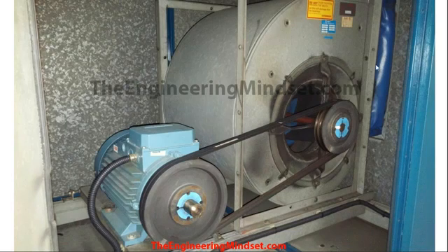So just to bring you up to speed with that, excuse the pun, we've got the motor here, then we've got the fan over here. Now these two are connected by the belt pulley. So this is the pulley wheel, and this is another pulley wheel. This is the fan pulley wheel, this is the motor pulley wheel. When the motor spins, that's going to transfer rotation through the belt and into the pulley of the fan, which will rotate that. And as that fan begins to spin, that's what pushes the air off into the building.